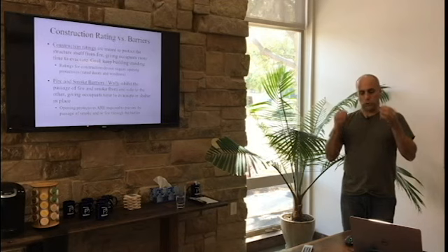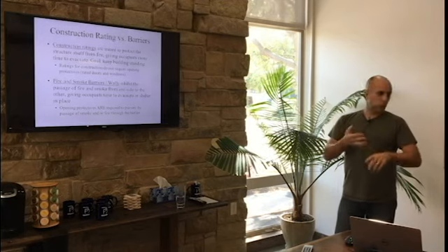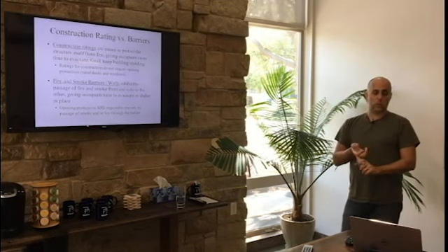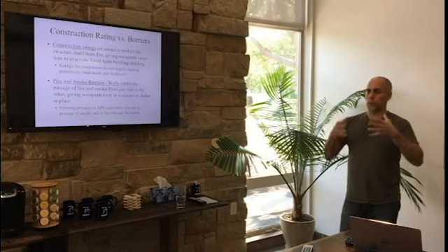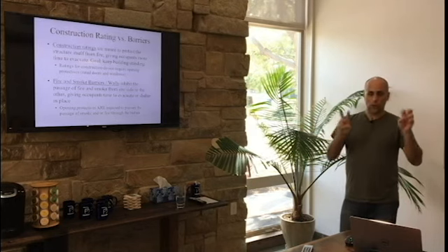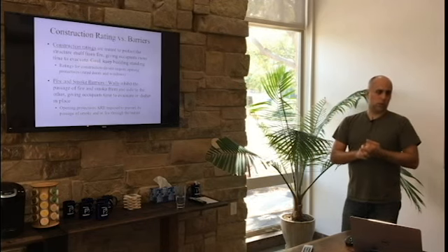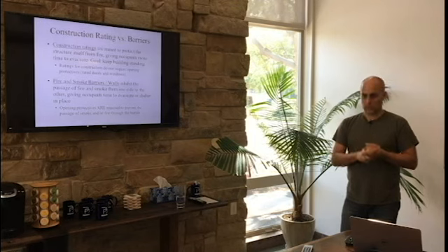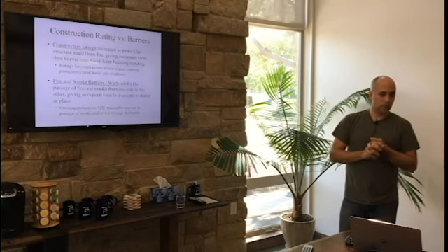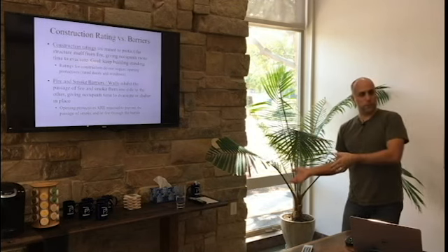Those are intended to separate corridors or separate exits or separate sections of the building into smoke compartments, or separate hazardous areas from other areas. The whole point of those is they are to separate. Those kind of barriers, you do not want fire or smoke to get past them. They may not be load bearing. It has nothing to do with that structure at that point.